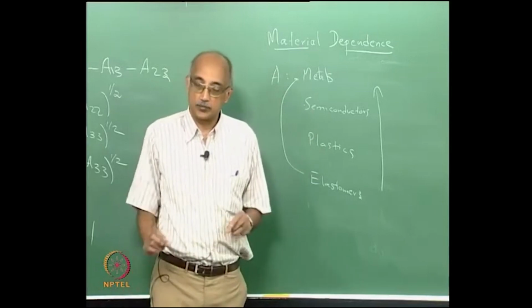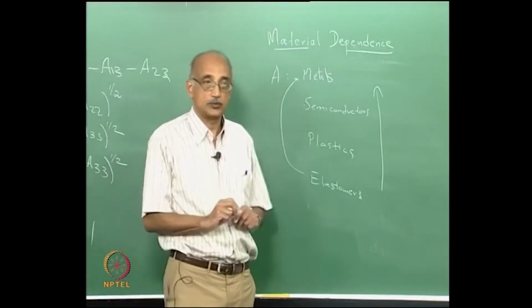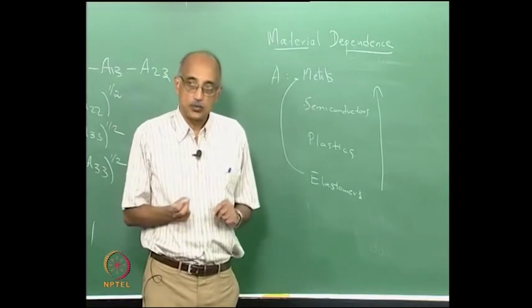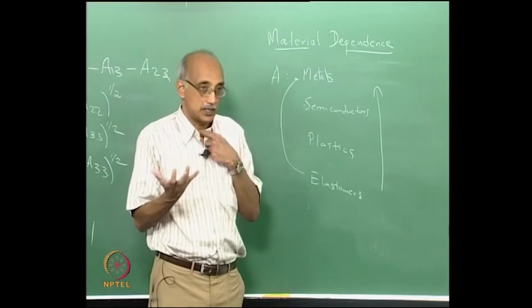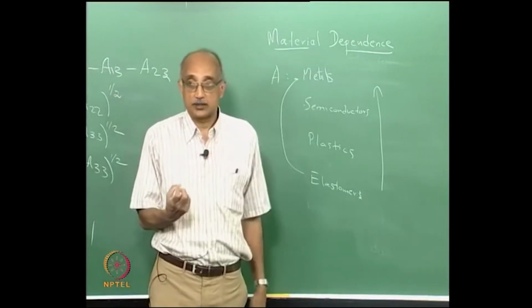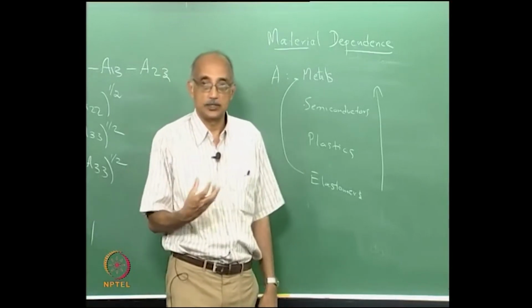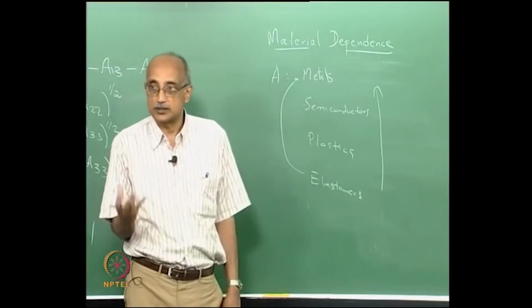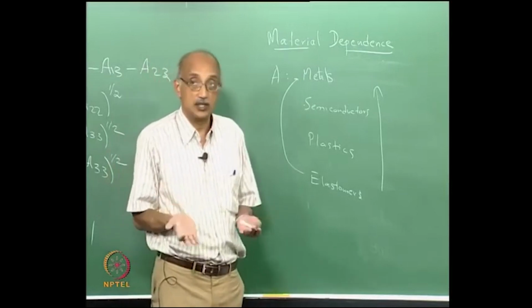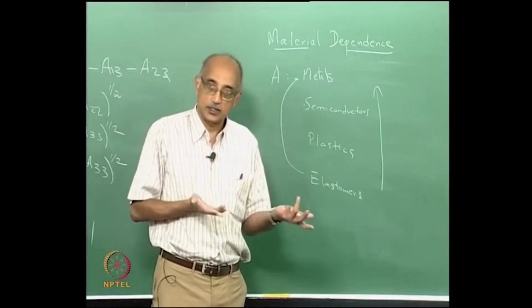That makes sense. But the problem is, from an electrical conductivity viewpoint, plastics are much worse. They are more likely to build up a static charge. So electrostatic attraction forces will be much greater when you use plastics compared to when you use metals. So the net adhesion force may actually be increased by using plastics instead of metals.